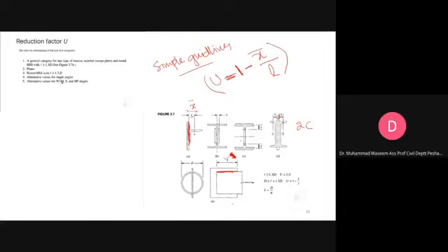Similarly, for the wide flange section, if the plates are connected here, you have to use this X bar; if they are connected here, you have to use this X bar. This is a simple equation. How can we obtain this X bar? You can obtain it from the shape tables in the AISC manual. Please remember what L and X bar are.